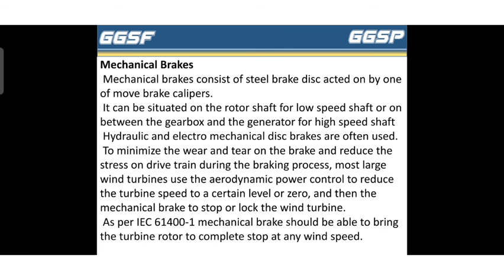Mechanical brakes. Mechanical brakes consist of a steel brake disc acted on by one or more brake calipers. They can be situated on the rotor shaft for the low speed shaft, or between the gearbox and generator for the high speed shaft. Hydraulic and electromechanical disc brakes are often used to minimize wear and tear on the brake and reduce the stress on the drive train during the braking process.